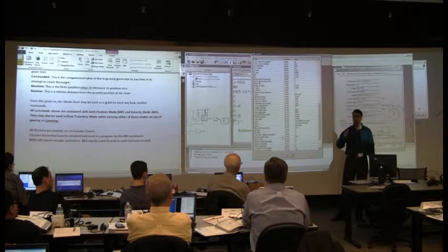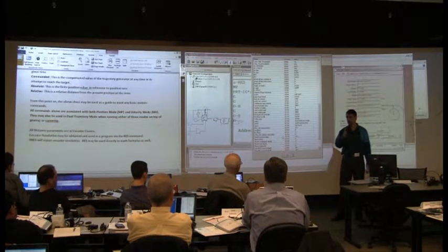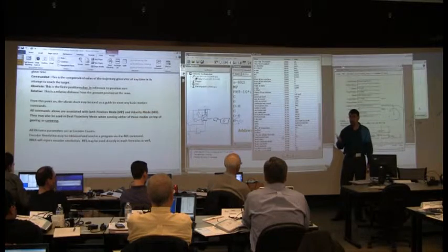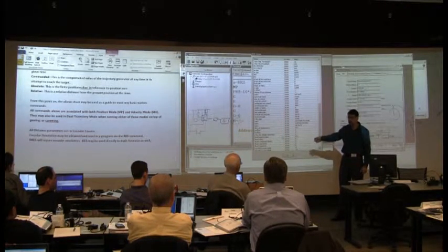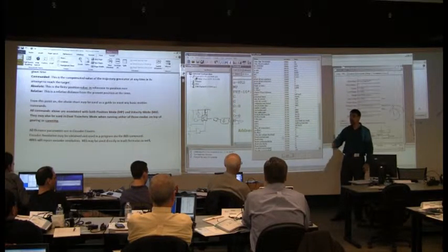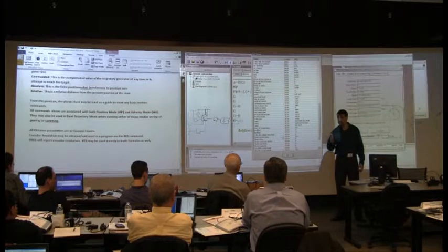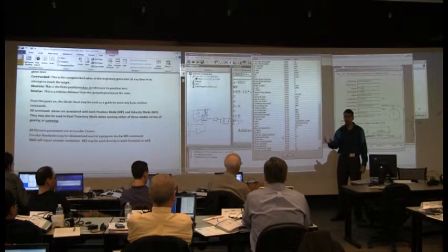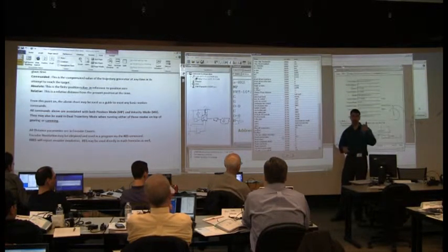Let's suppose you have a really slow-moving application. I mean, it's just moving snail-pace slow. You don't need that much voltage to run it. What's wrong with the bus voltage going way down? I'll give you another hint. It's moving slow, but it's a really heavy load. Power is power. If voltage goes down, current goes up.